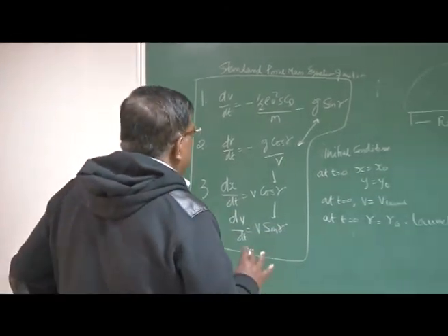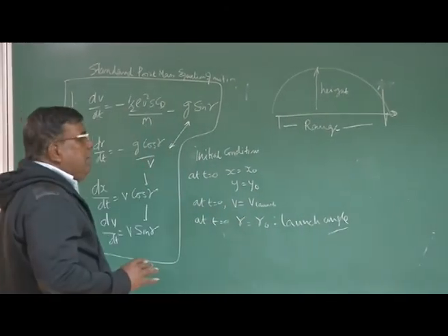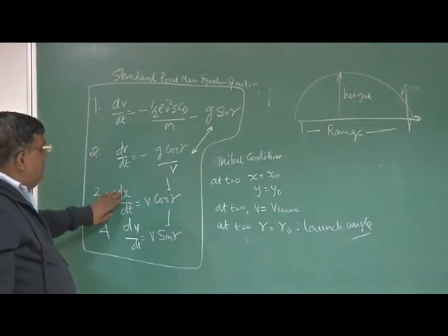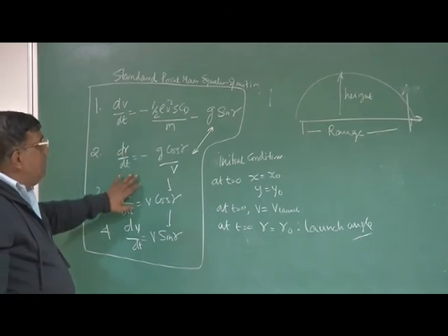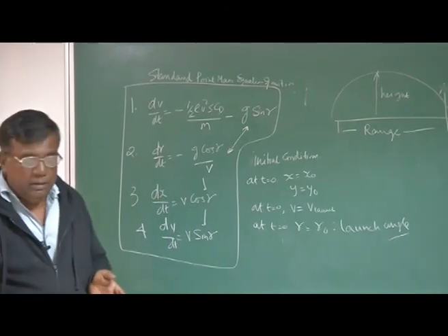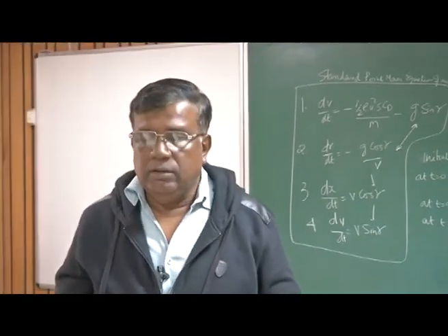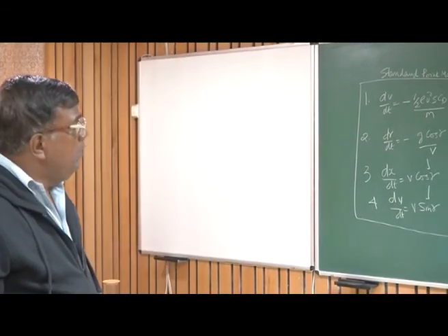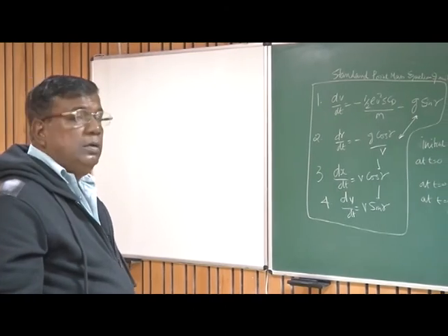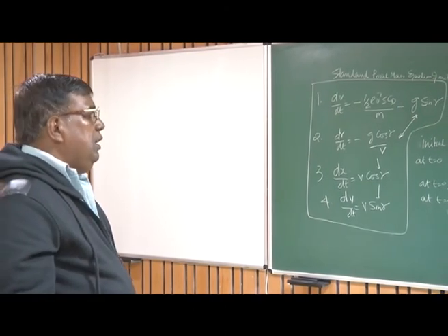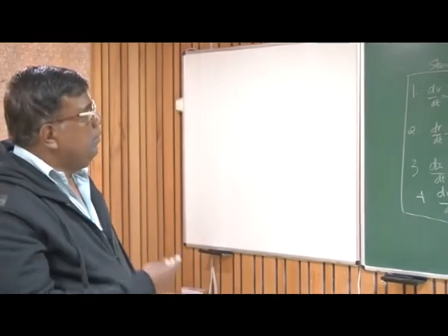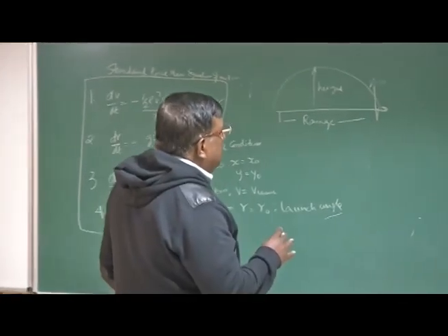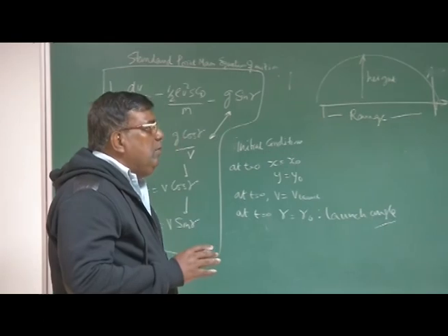In point mass, this is a fairly simplified way to write equations of motion, and you realize that these are coupled first order differential equations, and you need to solve them by numerical methods. You know that there are so many methods to solve these equations. If possible, we will be loading one or two software or code so that you can use it. But anyway, you can go to MATLAB and just solve this equation using a standard routine. This lecture is given to make you understand the simple point mass model.